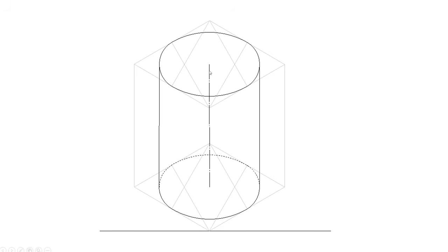Now you want to draw a chain line to represent the axis. To get the axis, first you draw a line from here to here and mark the midpoint. Similarly from here to here, mark the midpoint, and connect that, you will get the axis of the object. Now actually in this case the object is the cylinder, so only for the cylinder the solid line should be dark.